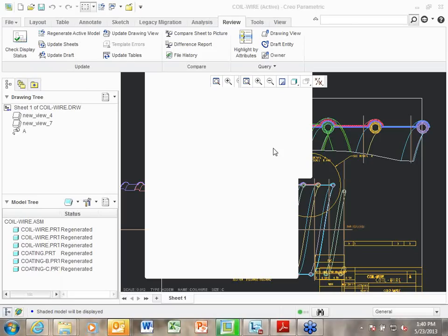This would completely change the variable in the program. In that case, I would have to reprogram it from scratch, or is there a simple way that I can update the geometry? There actually is a simple way you can update the geometry, and that is, take that wire. Let's say if I take that wire and make it round to square, I can have that as a variable within my family table and call upon one of those in my program.